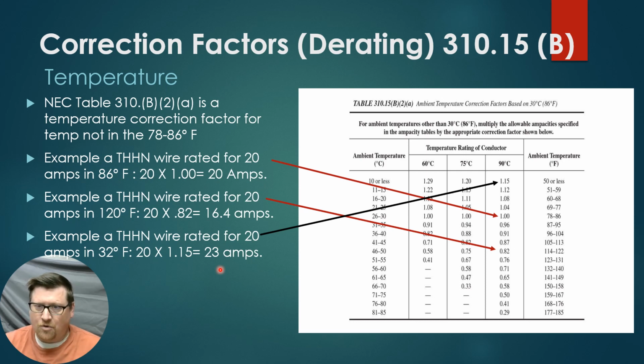Now, I'm going to be limited by the breaker and other factors, but I get to pad this up so that if I've got a bunch of these stuck in a single piece of conduit and it gets padded down, those things can counterbalance one another when I'm choosing my wire size and insulation type.